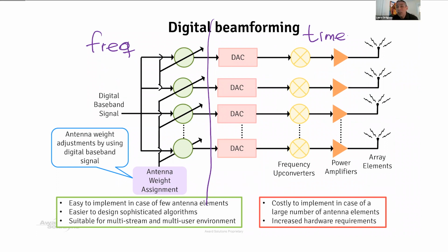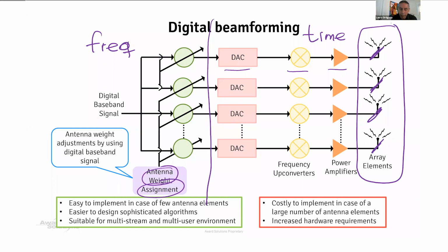Whereas if I have Alice in the other direction here, and Alice is receiving resource blocks, actually in this case, Bob, resource blocks, let's say 30 to 40, then I can create another beam in that direction. And if I have another friend over here, I can create another beam in this direction, right? So this will be resource blocks 50 to 66. That's the advantage of digital beamforming.